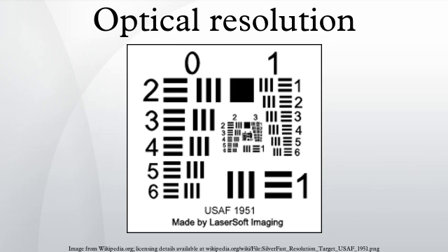Sensor resolution. Some optical sensors are designed to detect spatial differences in electromagnetic energy. These include photographic film, solid-state devices, tube detectors, scanning detectors, pyroelectric detectors, and microbolometer detectors. The ability of such a detector to resolve those differences depends mostly on the size of the detecting elements. Spatial resolution is typically expressed in line pairs per millimeter, lines, contrast versus cycles per millimeter, or MTF. The MTF may be found by taking the two-dimensional Fourier transform of the spatial sampling function.